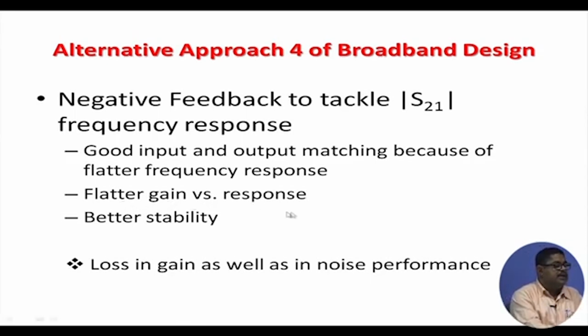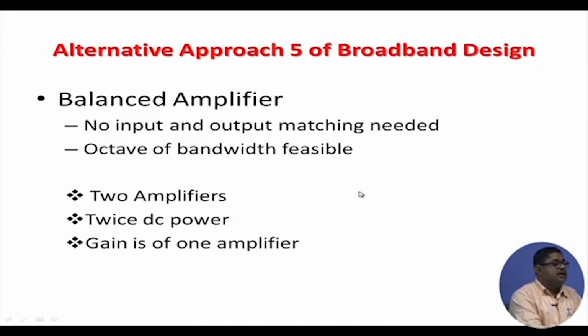So, you will get a flatter gain versus frequency response and better stability. Obviously, negative feedback makes any amplifier circuit stable, but here also, because of negative feedback, your gain as well as noise performance will degrade. But this is a very elegant concept.